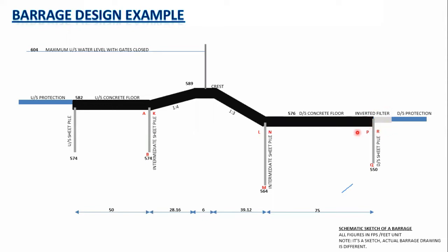If the soil particles are allowed to flow with the seepage moisture, it will cause tunnels, or it may cause piping on the downstream side. In undermining, small microscopic tunnels are formed due to displaced particles. And ultimately, they weaken the barrage foundation. As I said, the barrage foundation is nothing but just a concrete floor. And if the concrete floor is not supported by the soil beneath it, it will be displaced or it can be damaged.